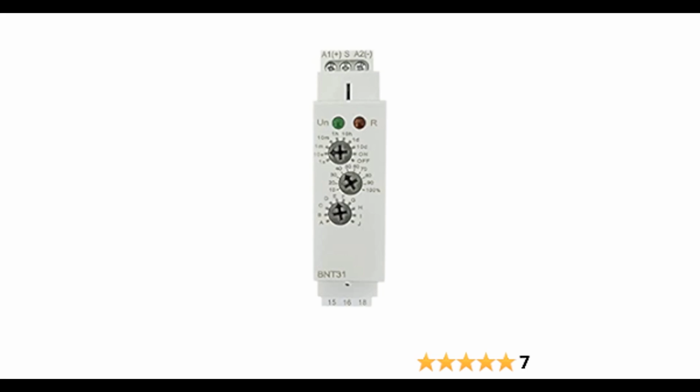Contact configurations in time delay relays determine how the relay interacts with the connected electrical circuit and load. Here are some common contact configurations found in time delay relays. Normally open, NO. In this configuration, the relay contacts are open when the relay is in its resting state, not energized. When the control signal activates the relay, the contacts close, completing the circuit and allowing current to flow to the connected load.